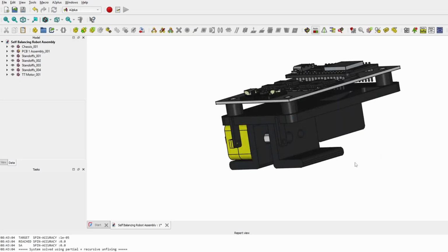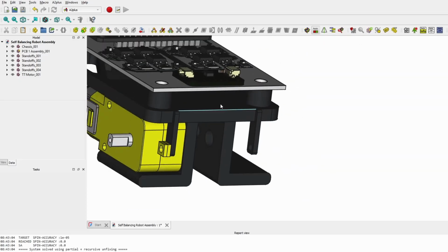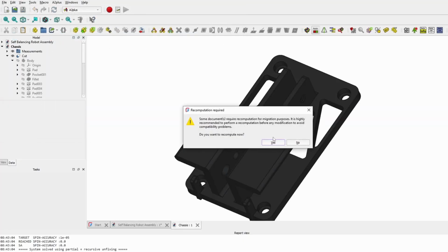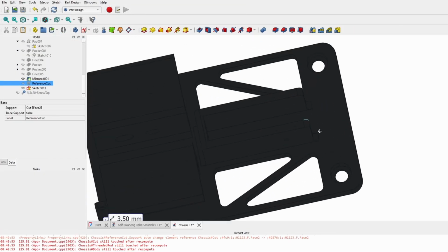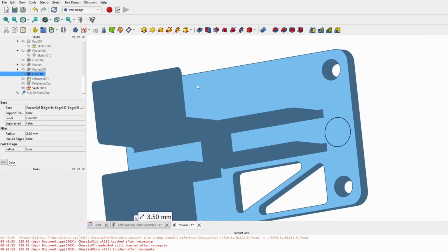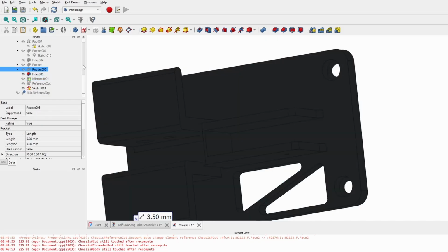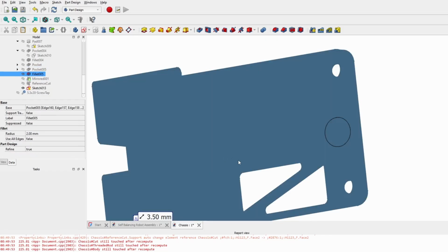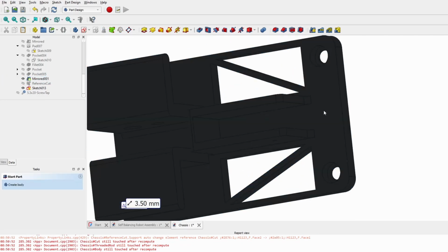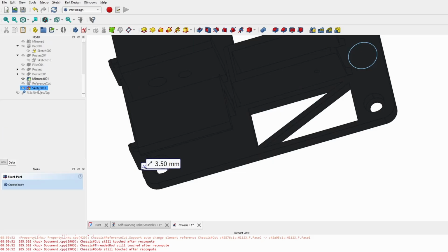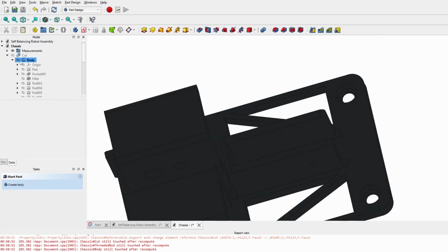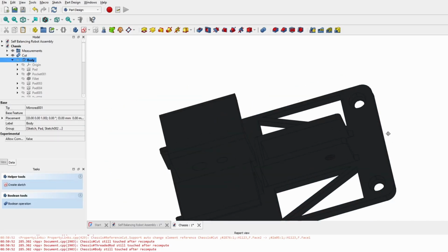So yeah, this is a partial finished design, but essentially you do the same exact thing over and over again. All right, so the cool thing about assemblies is that you can go into one of your parts, for example. Let's just assume that for some reason you want to get rid of these very nice filleted edges here. So for that, we get rid of this right here. If I just delete that, then when we go here, we shouldn't have that anymore. And the point is that if we change a model that's inside of an assembly, then we should have that same change in the assembly.